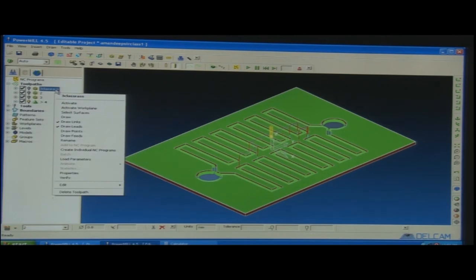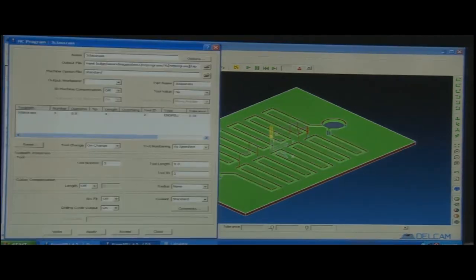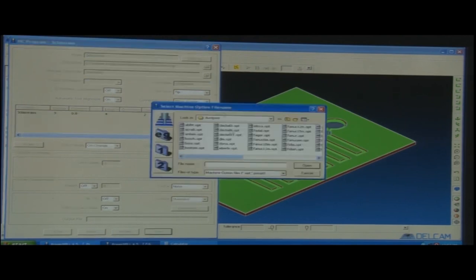So, we can also store the same program somewhere and try to redo this program multiple times, and also, okay, let me put the output file, in which form would I like to get the program. See, there are certain options here, you can see this, there is FANUC, there is Heidenhain, there are different kinds of formats, hundreds of controls are available in the market nowadays for different types of machines.